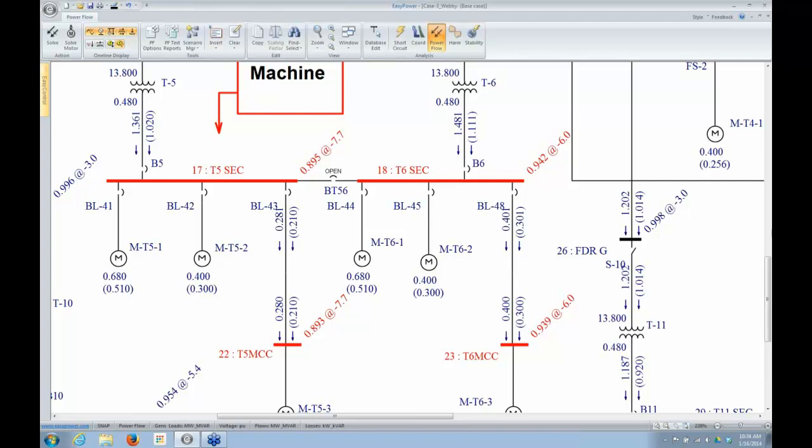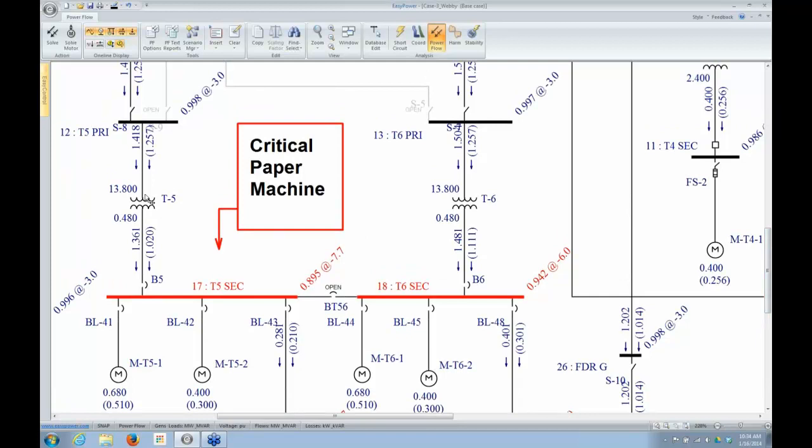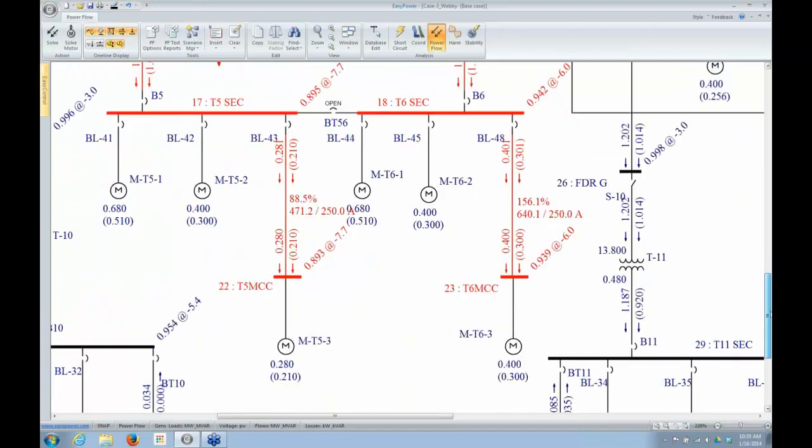So you can see I have, turn my voltage violations back on. You can see I have some things that turned red here. We're going to just talk about those briefly. So we saw in that little model I had before, when the voltages get low, they turn red. So in this case, we see this voltage is 0.939. That's below my 0.95, so that turns red.